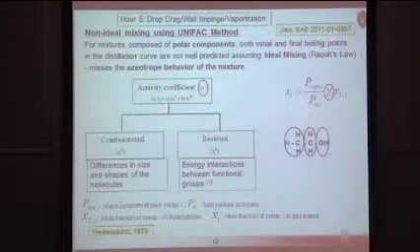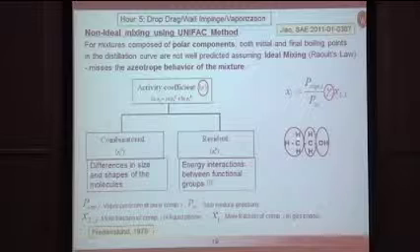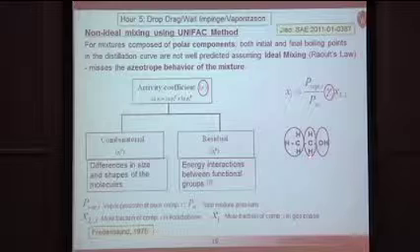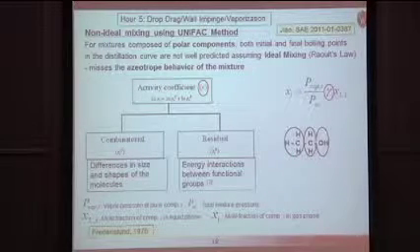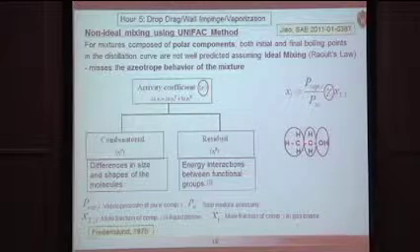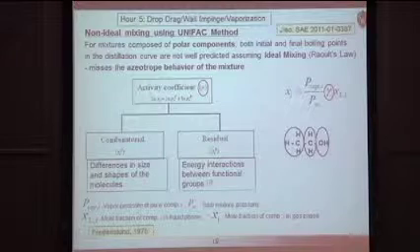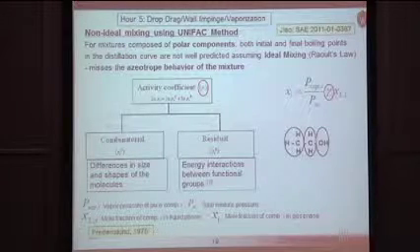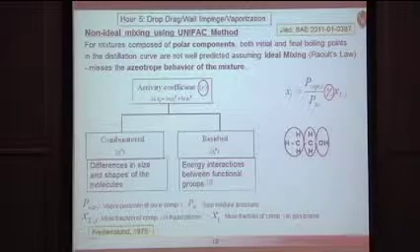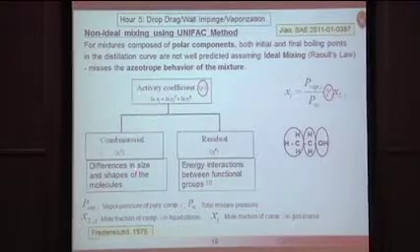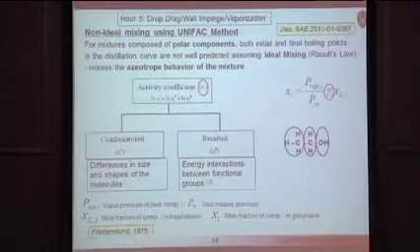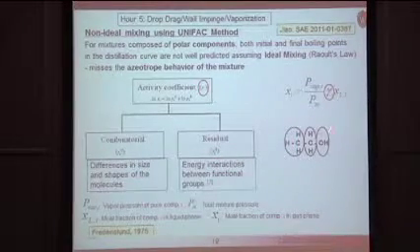So, for example, in the UNIFAC method, you would break up your fuel molecule, in this case, say, for ethanol, into these functional groups. CH2 here, OH, CH3. And it has basically tables in the code that will tell you how these functional groups will interact with functional groups from the other species in the mixture. So if we mix ethanol with gasoline, it will take that into account. The activity coefficient consists of basically factors that take into account difference in shapes and sizes of the molecules, and then interactions or energy interactions between these functional groups.